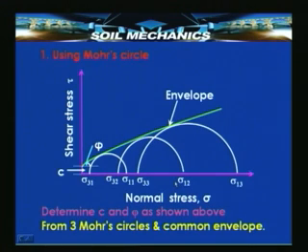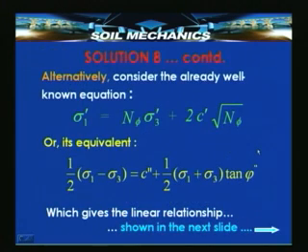Here we have the typical Mohr diagram, that is, we have 3 stress values, minor principal stresses corresponding to 50, 150 and 250, and 3 axial stresses. What we need to do is to plot 3 different Mohr circles and then plot a common tangent. Now, that is not shown here, the Mohr circle plots are not shown here. However, the student may attempt drawing these Mohr circles and draw a common tangent.